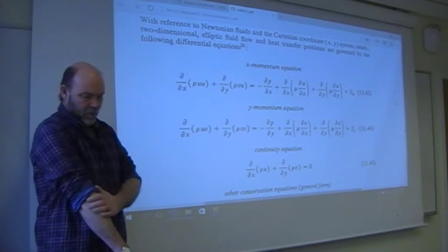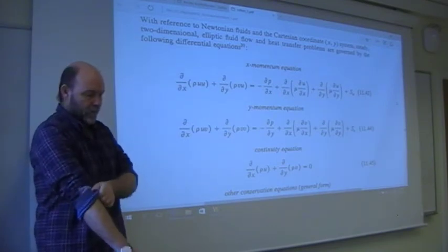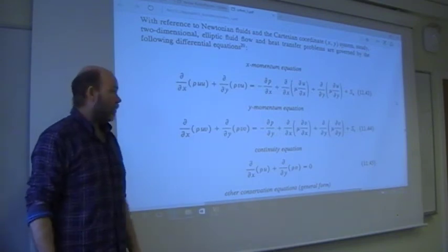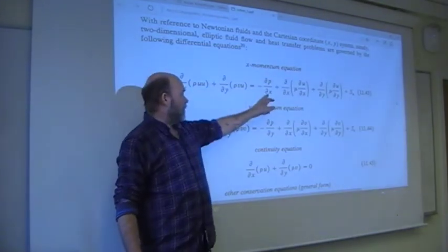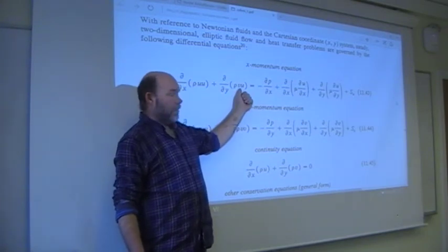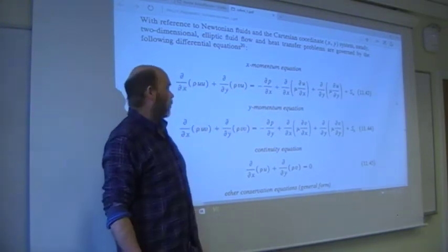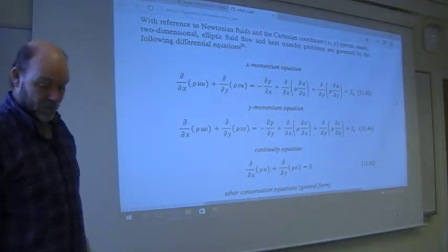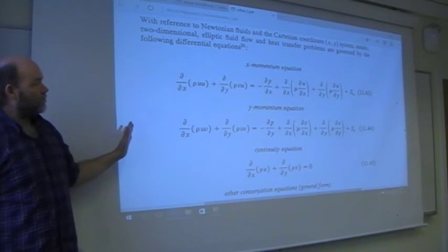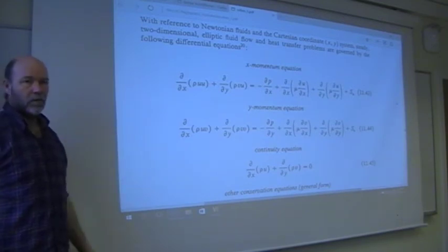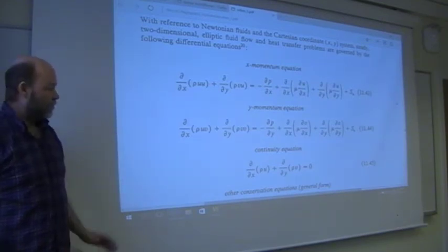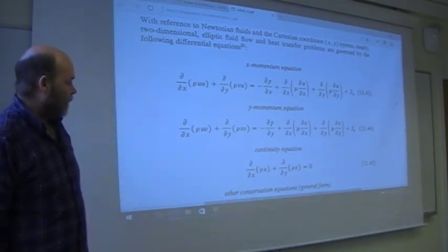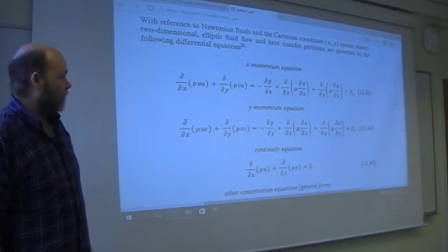So very hard to avoid. But modern techniques, which they have used for some years now, use some interpolation tricks to couple the local pressure in the same location as the velocities, so that you can avoid this. And this is definitely the most popular. But when this was written, that was not state of the art. So here they use a staggering idea. Makes it a little bit messy, but still possible.